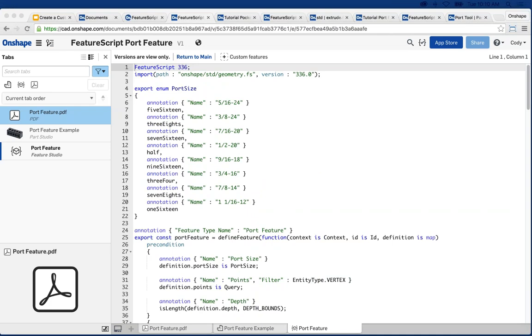So if I wanted, for example, to extend the extrude command to an offset from surface option, I could copy all the default extrude code and then add the additional thing, and that's fine. Yes, and you could build your own option into the standard extrude command if you want, or into your own custom version of the extrude command. It's important to keep in mind you can't change the standard extrude, the button that's in this toolbar, but you can absolutely create your own button in the toolbar that has that option.